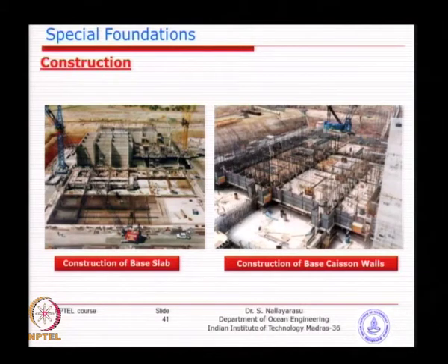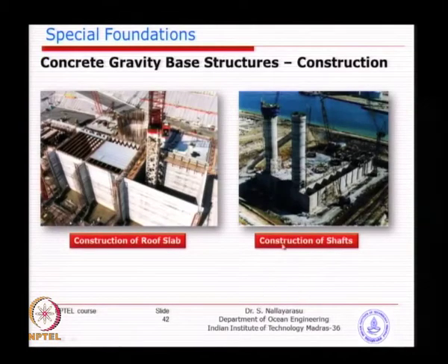So you can do it in a sequence, and then you do the raising of shafts, which is also very shallow. In this particular project they were trying to do everything and then float out. Typically about 6 to 10 meters is the height of the base, and depending on the water depth, shafts of 3 meter, 4 meter, up to 10 meter diameter are constructed.